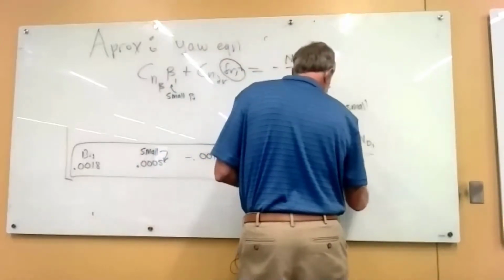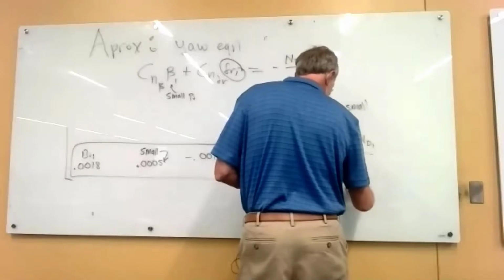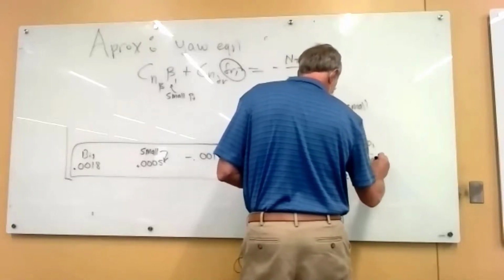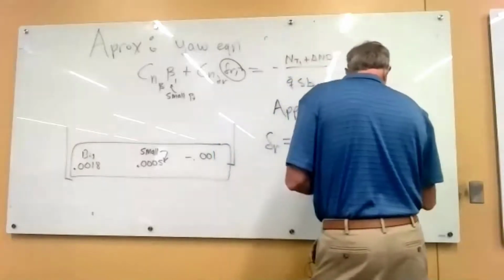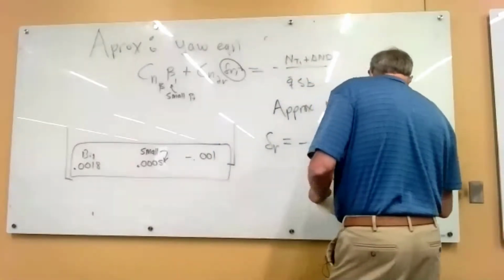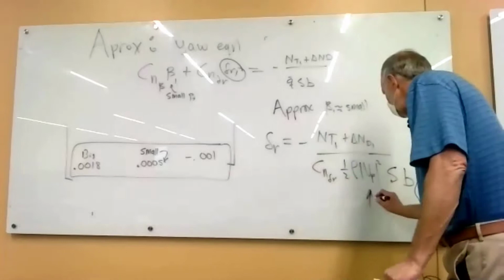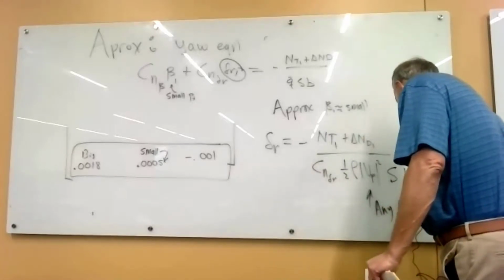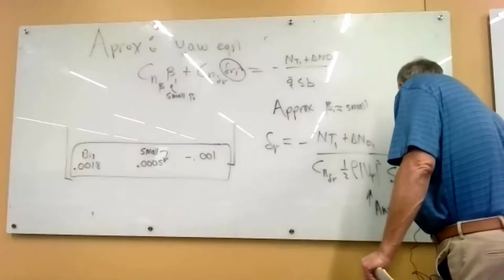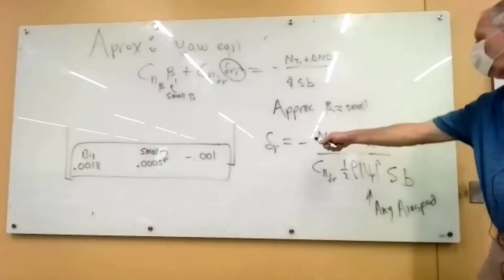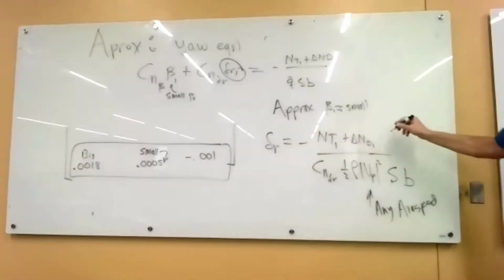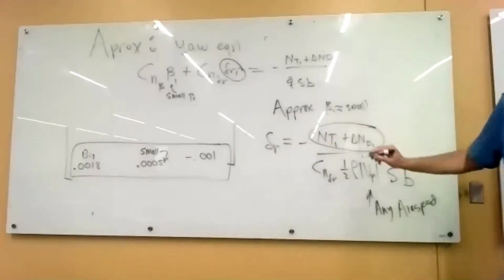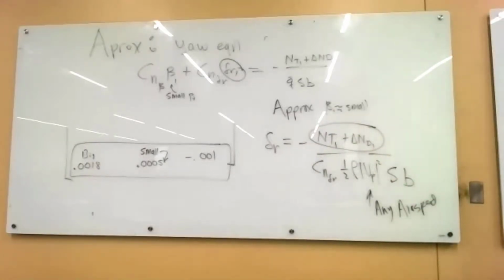And I'm going to write out the dynamic pressure. So for any airspeed, we can find out how much rudder we need to counteract this full throttle engine yawing moment.